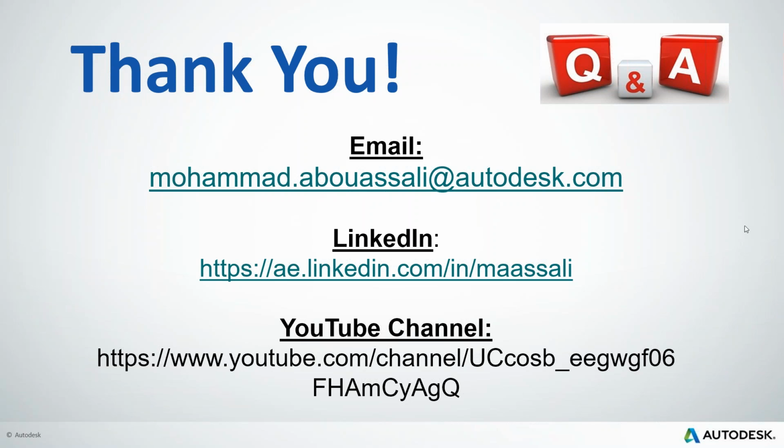Okay, so we started to have a couple of questions. Let's see. Okay, how to make custom bridge templates. From within Infraworks, if you right click, there is an option to create a bridge template, which you can then use in your upcoming designs. If you like, Abdullah Jamil, I have the email address of each and every person who's posting a question, so I'm going to put remarks and send you a link that helps you create those in detail. So Abdullah, I'm going to send you the link for the templates.